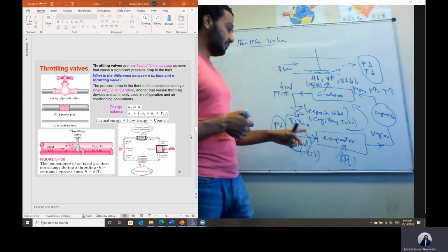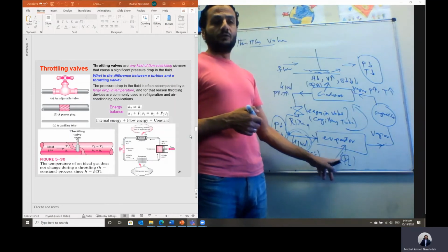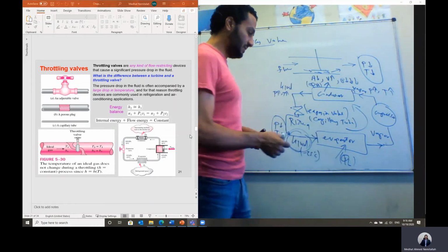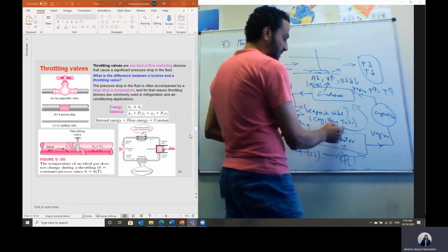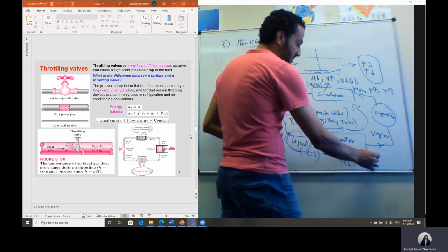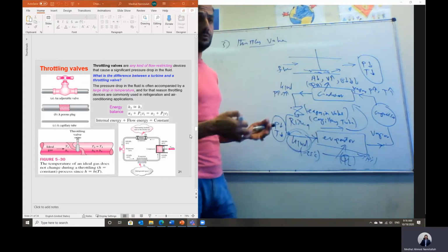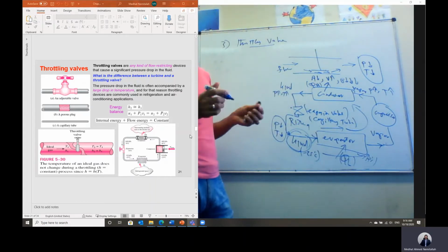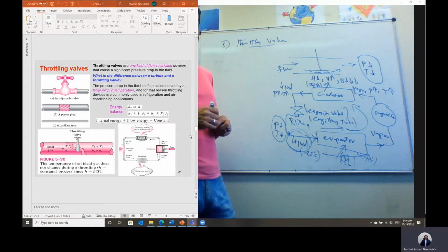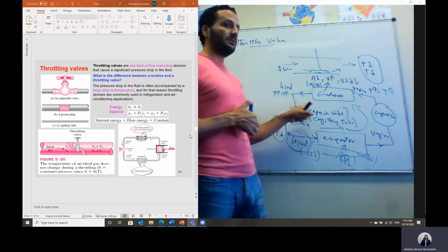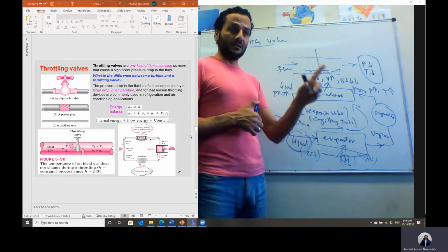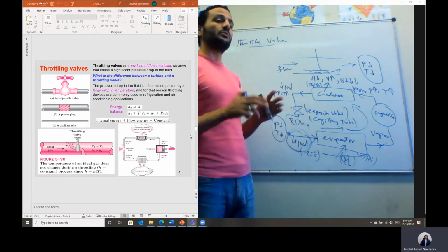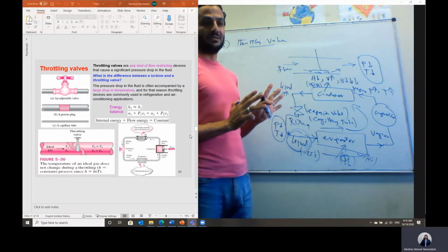Okay, so in the air conditioning system, instead of cooling down a food compartment, we are cooling down the surrounding air. So we come up with air. This air is passed inside this evaporator. It will cool down. Then we can take this air to a given room to cool it down through the air conditioning system. So the same cycle is applied in the refrigeration system, like the fridge at your house, and also in the air conditioning system, typically the same cycle.